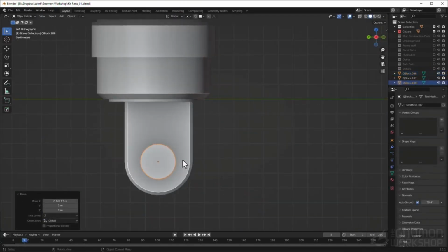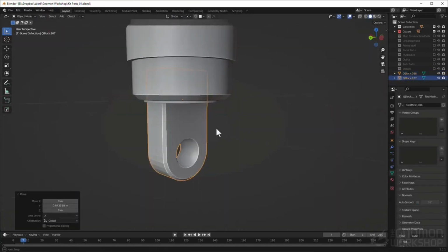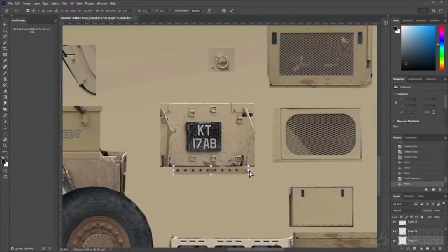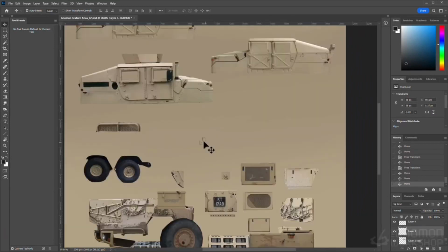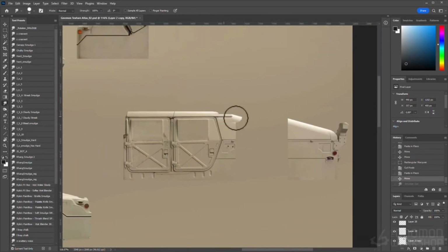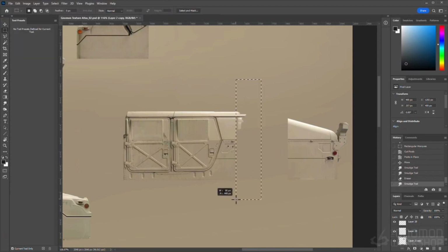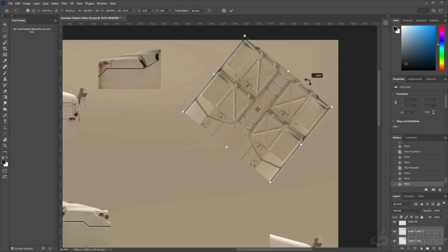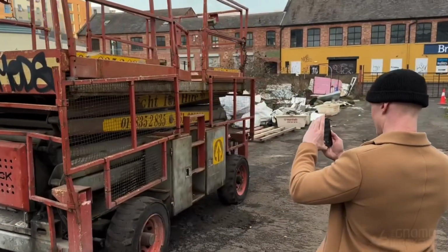This is the part that takes the longest, but a bit of time investment early on leads to a lot of time saved in the later parts of the design process. You then need to texture your pieces before doing anything else so that you don't need to individually texture the parts after creating the sub-assemblies and the mech designs. You can do this a number of different ways, but I prefer to use one or two texture atlases to save memory in Blender and make modifying the materials easier.